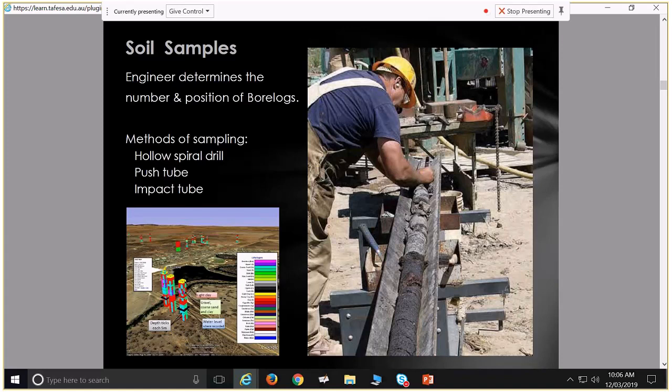Yeah, the only way I've seen it done for inaccessible areas is with a two-stroke motor with a rammer on it. And I imagine with a lot of the soils around Adelaide, for a pool, you'd want to be going down around 2.5 metres to see what's there. And I imagine I'd still be using the two-stroke motor to ram the tube in. But I've also been assessing sites out with an engineer.